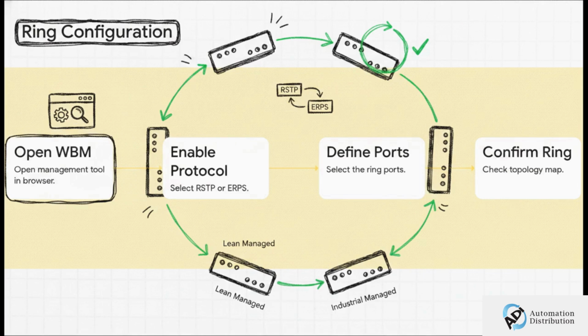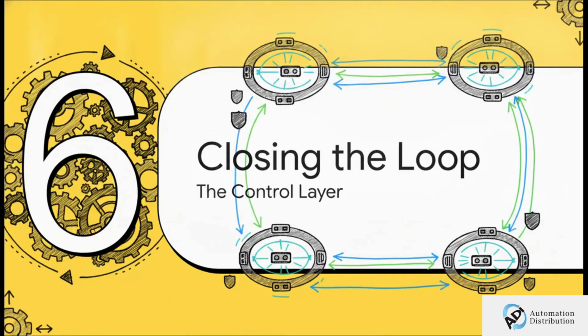What's really cool here is that as long as your protocols match, say everything is running RSTP, you can actually mix lean managed switches at the cell level with industrial managed switches at the backbone level, all within the exact same ring. Okay, let's bring it all home.